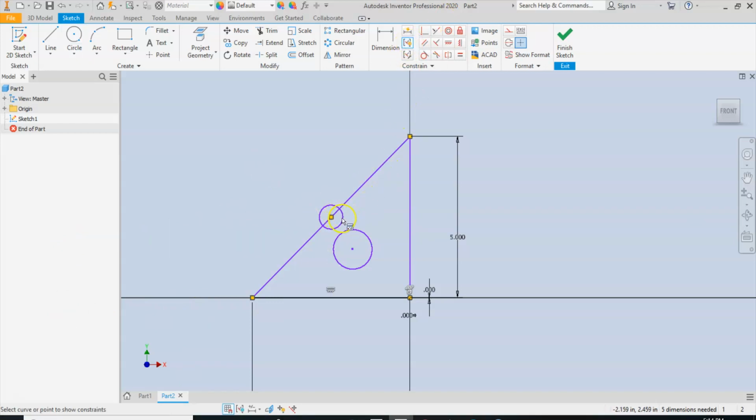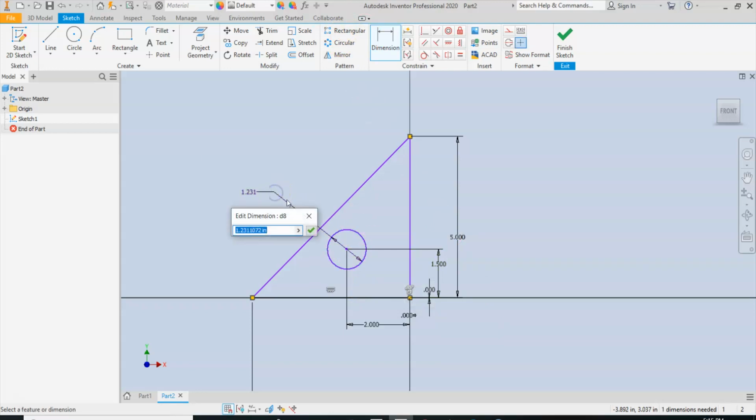So take a look at that as you are working on your drawing, and make sure that you are locating that in the right place, and that you're not misplacing something. So I'm going to use the dimensional constraint to locate the circle. I'm going to put that at 2 inches, and then making sure every time we put a circle in there that you're identifying it with an X and Y axis, and then also putting the size. So the size defines the size of the circle. So we've located it in both directions, and I've put the actual size of the circle.